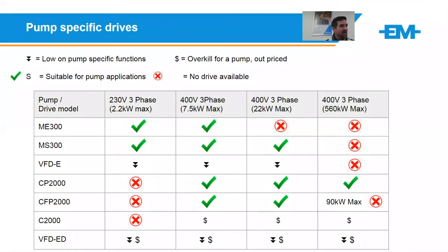The Delta HMI has a host of built-in drivers. You can just go select, I normally use the Delta ASCII controller, and from there you can select Delta inverter and target the address you want to display on the HMI. Change the ID if you've got more than one drive. It really works well directly from the HMI to the drive's built-in Modbus RS485.